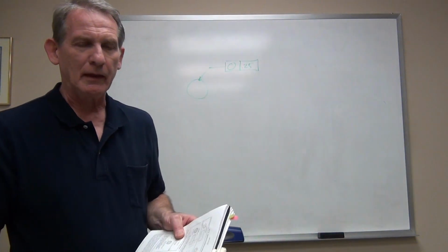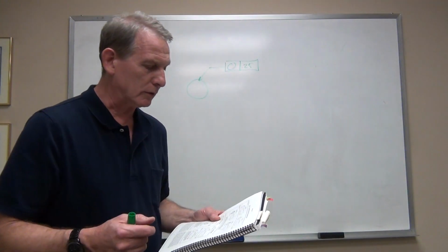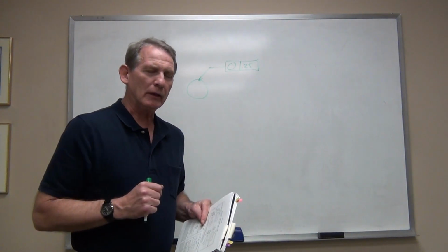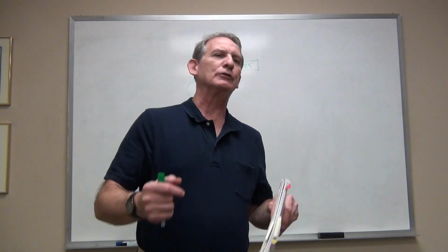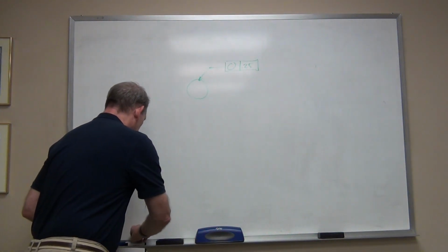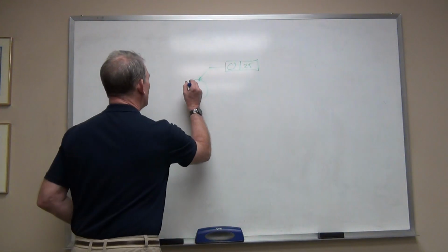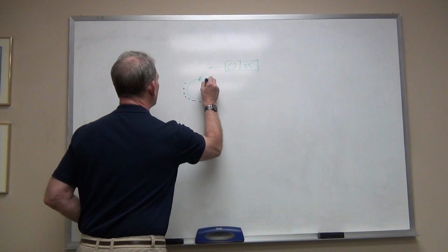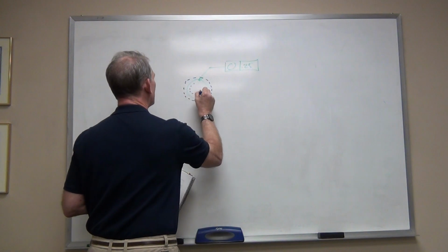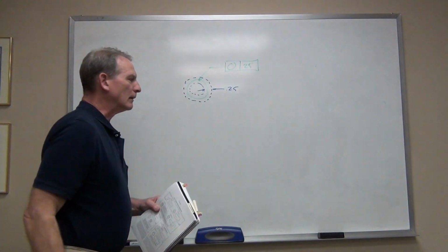So what does that mean? That means that we have to have a tolerance zone. We know the tolerance zone is 0.25. What's the nature of that tolerance zone though? Now all of a sudden we've got a different shape, so we're going to have a different shape tolerance zone. In this case, we are going to have two boundaries. We are going to have an outer boundary and an inner boundary.